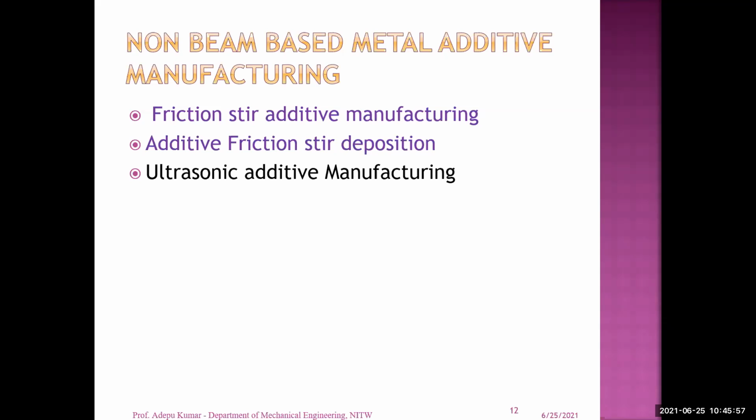So in that case, you need to protect from the environment. Then you can choose helium or argon as gases, which are responsible for not reacting with the environment. So your problem is solved because of these gases used during the additive manufacturing process. There is no chance of oxidation.